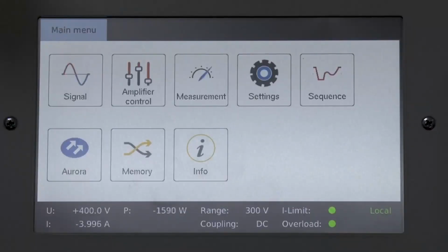Looking at the power amplifier power sign, which is negative, means the power is flowing from the AC grid to the DC bus. So, earlier it was DC bus to AC grid and now it is AC grid to DC bus. The DC bus voltage is always regulated to 400 volts. From these test cases, we have witnessed the energy exchange between the AC grid and DC microgrid.